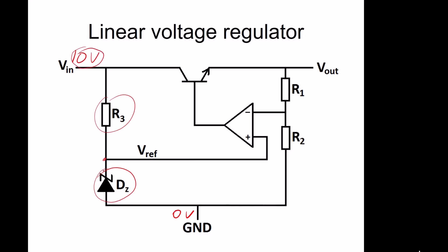So instead of using a resistor for this low component, we use a Zener diode. If you think back to our lecture on Monday, a Zener diode is used in reverse bias configuration, and it is used that way because there's a very specific voltage drop across this device.